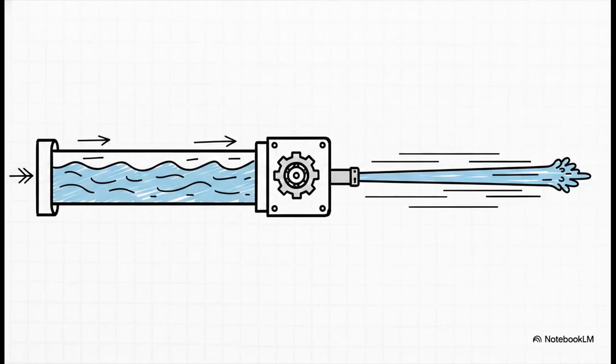Okay, so our main goal here is to step up that 130 volts DC to a tightly regulated 320 volts DC. Think of it using a water pressure analogy. Our solar panels are basically giving us a wide, slow-moving river of water. It has energy, sure, but the pressure is just too low, only 130 volts. We need to blast that water out of a high-pressure hose at 320 volts. To do this, we don't just squeeze the pipe, we build an electronic pump that rapidly builds up pressure and releases it over and over again. That pump is our boost converter.